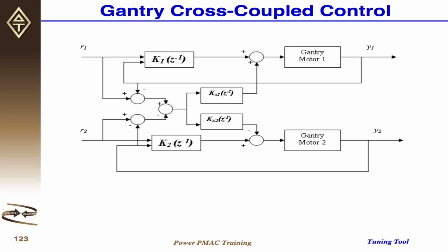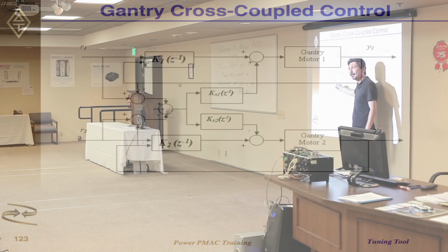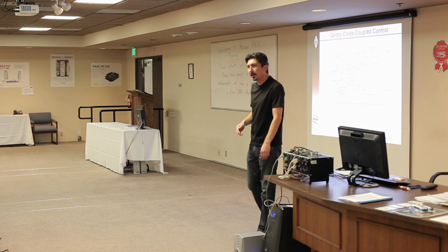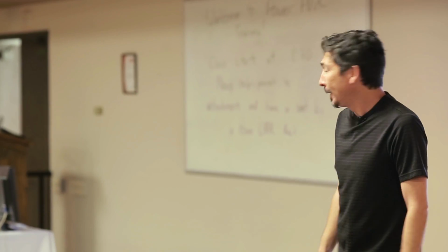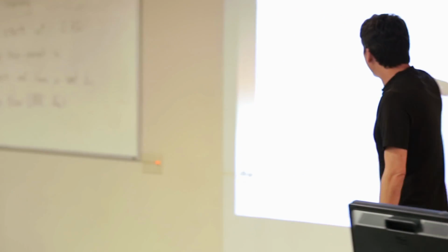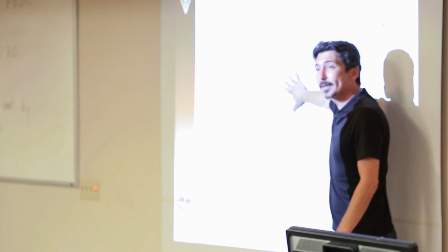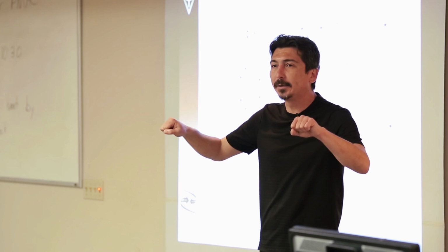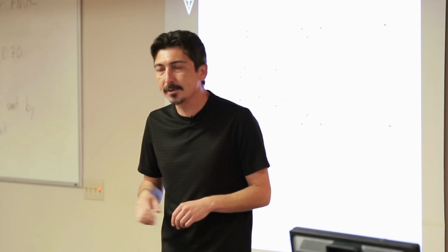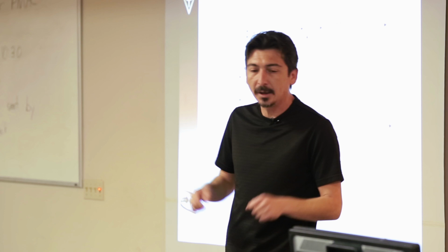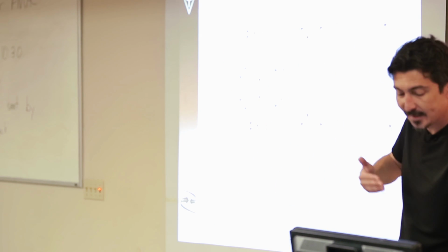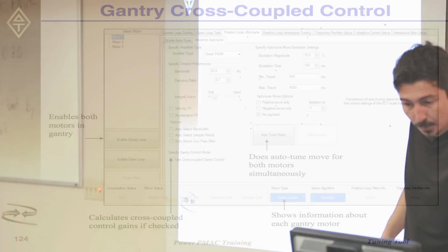Most of the time, what I call the following error between these 2 motors is called Gantry following error. It's going to decrease it by half, or a third, with the addition of this. And of course, if there's any disturbance, without this, these Gantry motors are not coupled, so they are completely independent. So this always helps to minimize the skew with any moves.